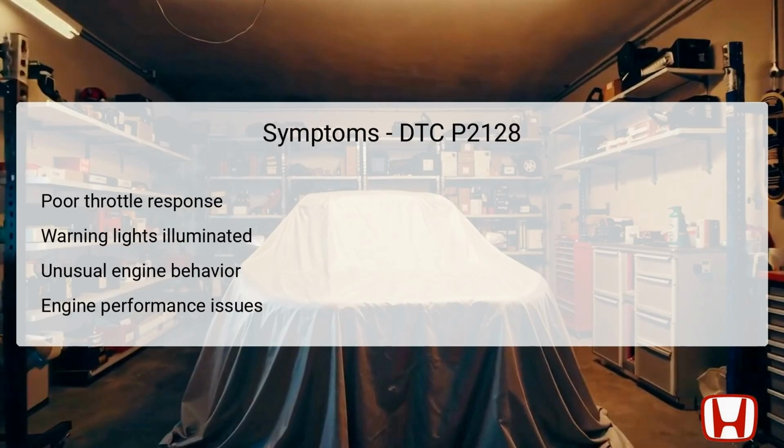When experiencing the DTC P2128, several symptoms may indicate underlying problems. One of the most prevalent symptoms is notably poor throttle response. This is when the vehicle fails to accelerate as expected in response to pedal input. Drivers may also notice warning lights illuminated on the dashboard, often including the check engine light, which signals that the vehicle requires immediate attention.